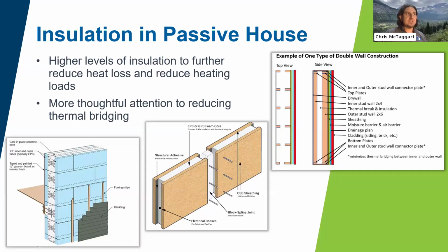Now, look, passive houses also do have space heating systems. They do, in fact, get heated almost always. You don't see passive houses that are unheated. That being said, the idea is that instead of having heating be, say, 60% of our energy budget, as it is in a conventional home, it ends up being 10 to 15% of our energy budget.